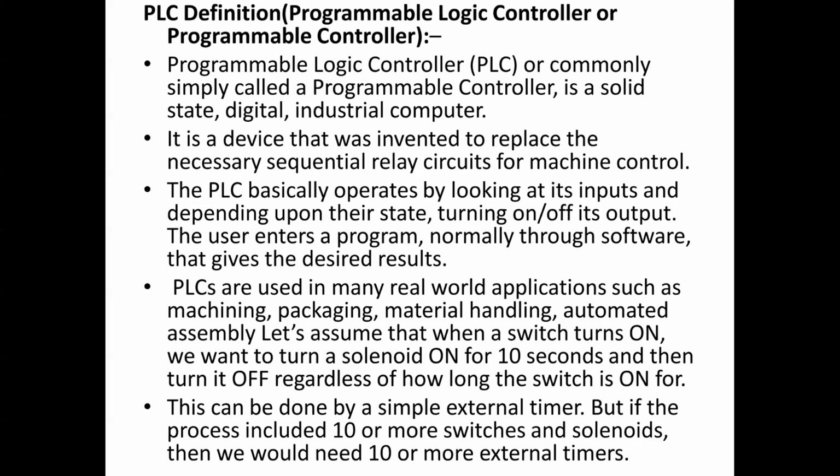Okay. So PLCs are used in many areas, that is machining, packaging, material handling, and so on. We want to turn on a solenoid for 10 seconds, then turn it off, regardless of how long the switch is on for. Okay, so that is how we are going to replace this relay system. With PLCs, the solenoid is there. We have to turn it on for 10 seconds, and after that we have to turn it off.